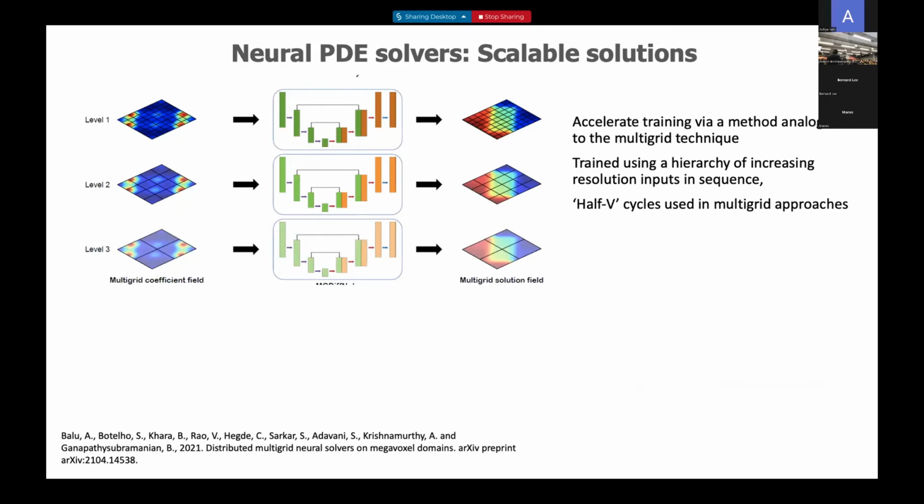If I take a 512 cube simulation, this takes 20-30 minutes on a reasonably sized computing processor to run. And each time I want to try a different input microstructure, that takes me 20-30 minutes to perform a simulation. So what we were able to show, and this is the link to the scaling invariance that Rose was talking about, is that we can essentially have a multi-grid filter. This is like transfer learning. Take a smaller unit with a 32 by 32 by 32 mesh, train this, use those trained parameters for 64 by 64 by 64, use that for 100 and so on.